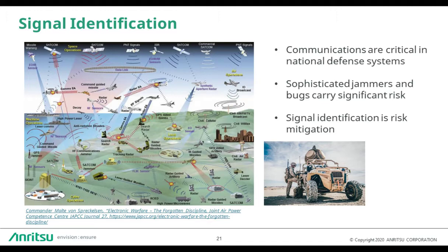So, for example, if it's some type of smart jammer, as you're doing your communication, you see it with a spectrum analyzer, that jammer signal may be completely hidden inside the envelope of your radar pulses. But as you pull out the IQ and slow down the playback and look, you may see that jammer come in and start to track your radar. And as it tracks your radar, you're able to zero in on what it's doing, figure out its tracking algorithms, avoid them, and continue to manage your communications in that way. So that's why signal identification can be extremely important.